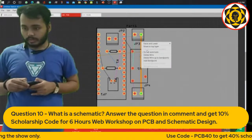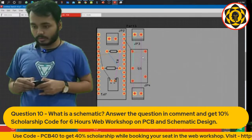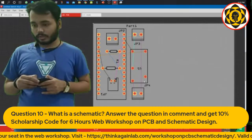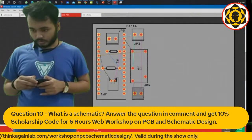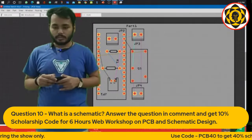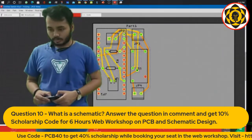We're going to use auto routing. One more reason I'm going to be using auto routing is because it routes in both directions, so you don't need to worry about if it goes to the top or to the bottom. The auto routing will take care of that. That is sorted. As you can see, we now have a defined territory. So now we can simply do auto routing, with all the conditions selected.